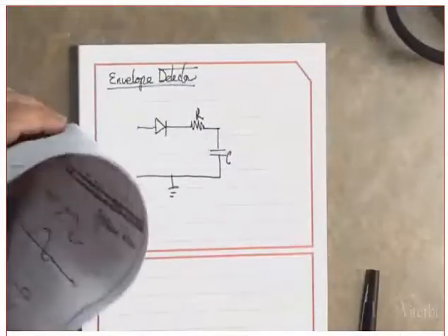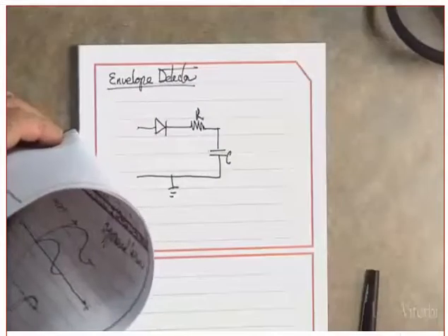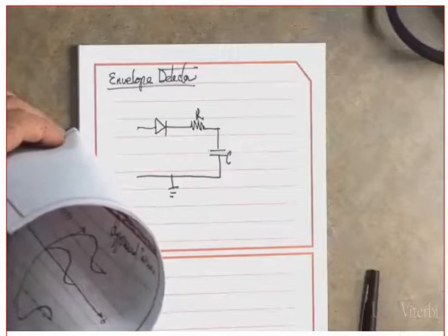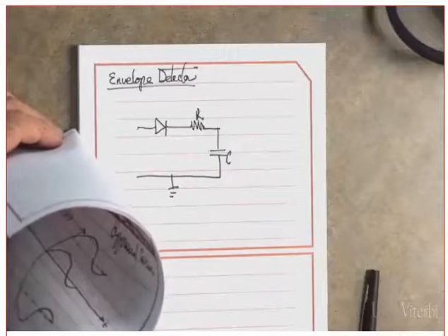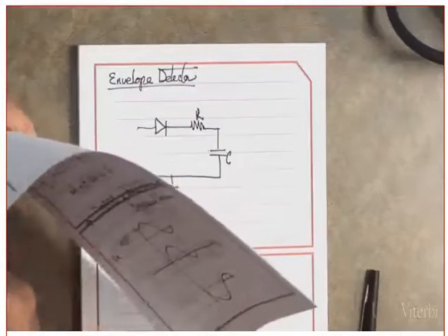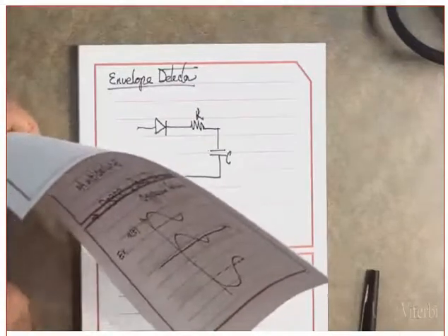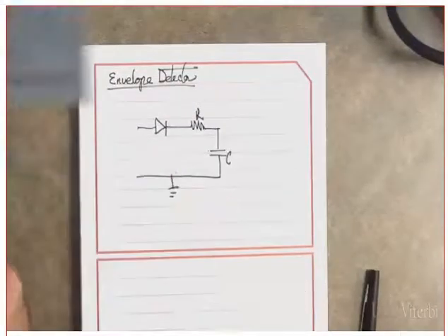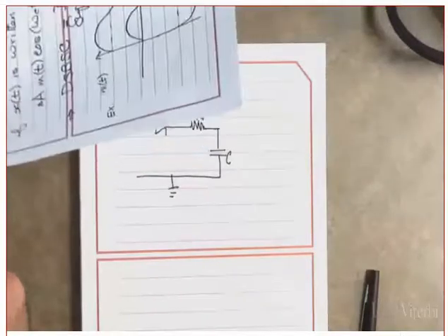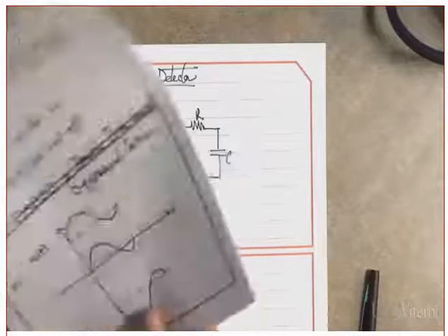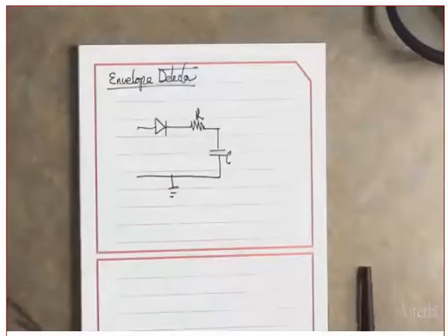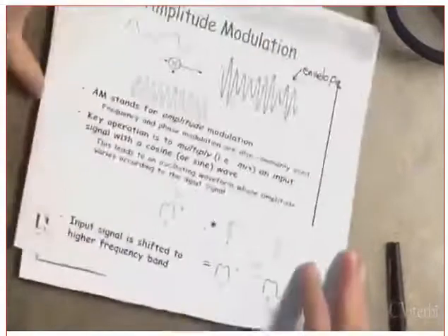The beauty also of the AM, just regular AM, is that when you are transmitting this carrier component, that carrier component will help the receiver generate a locally generated carrier, which is in synchronization with the carrier that you are sending. But what is the problem? The problem is that you are going to waste power transmitting a carrier component that carries no information in it whatsoever. Clear? Okay. Now, let's get back to the charts and try to understand a little bit better.